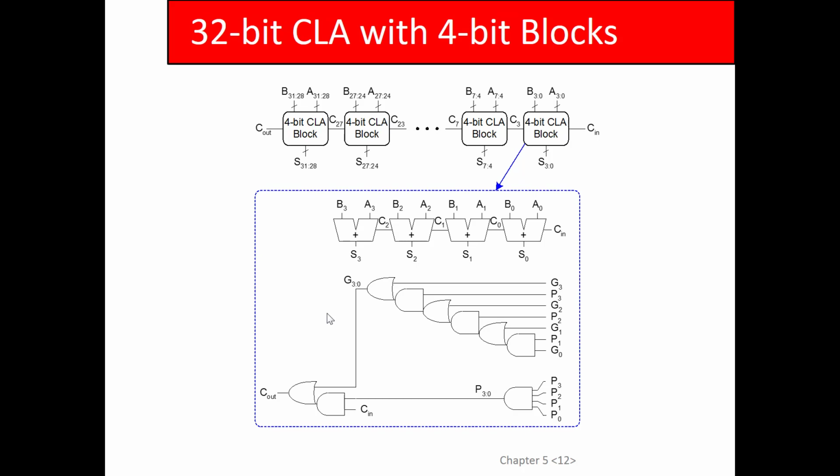It's the group of 4 bits that's second to the most significant bits of the sum. You would calculate its carry in by looking at the propagates and generates from the previous 6 groups of adders. You guys with me? Does that make sense? Not sure how well I'm describing this.